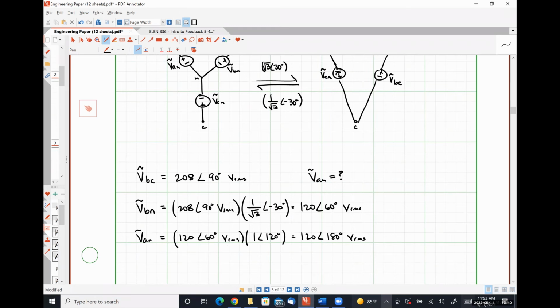So the conversion factors that we've developed specifically go from the A phase of one source to the A phase of the other source. But because we know that our systems are balanced, once we know what phase we're in, we can shift to any other phase we want. So we go from Y to delta or delta to Y, and then we rotate the phase to the one that we need. Okay.